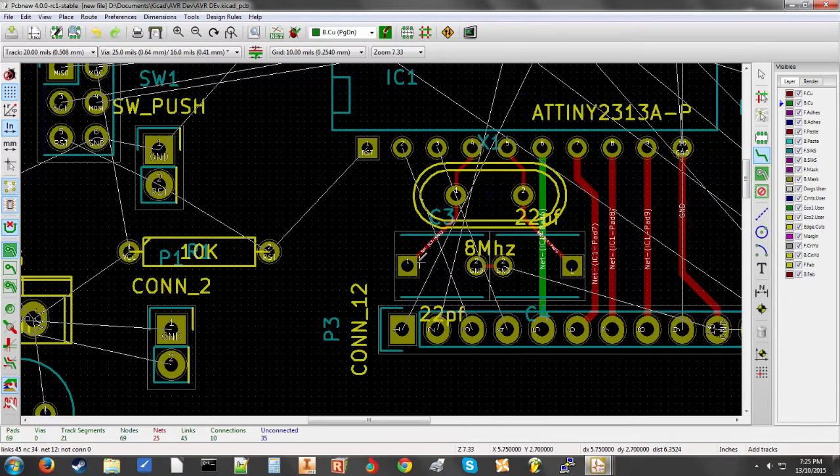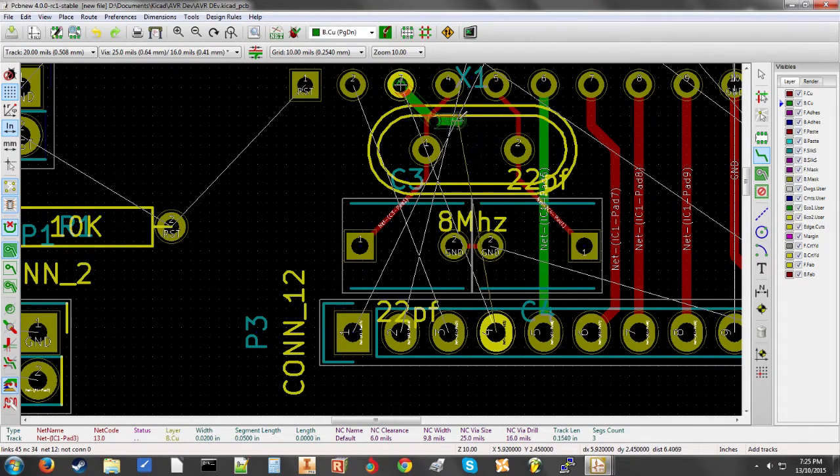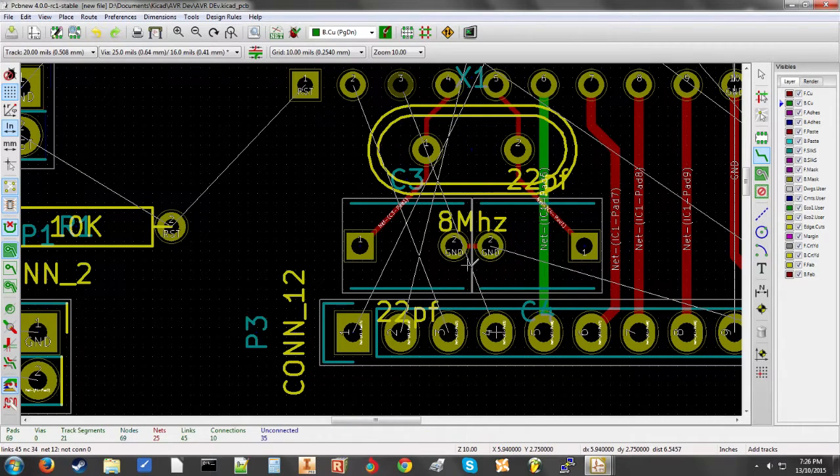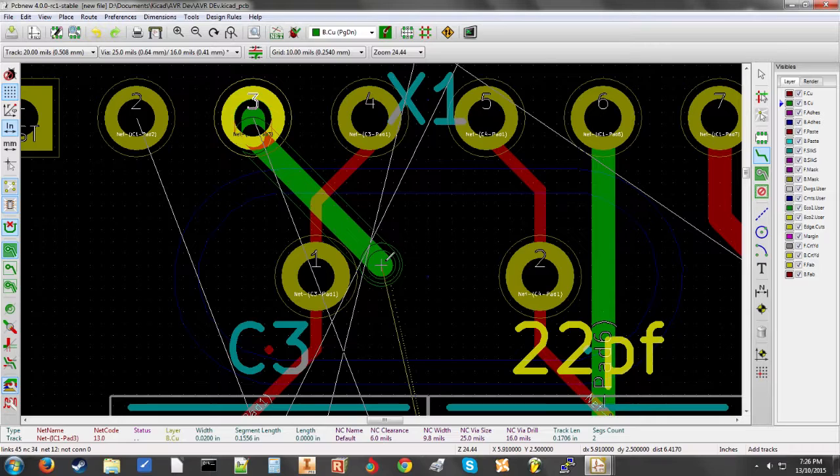We're going to undo that because that's not the best way to draw that line. And we'll just draw another line here. And now you're just going to basically position components in the best way, making sure that the fine outline around this trace and the fine outline around those pads, you want to make sure that those never touch.